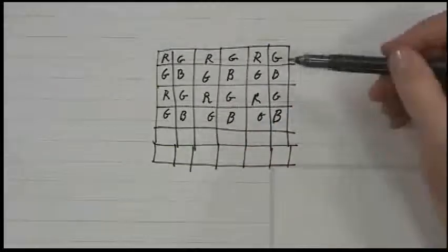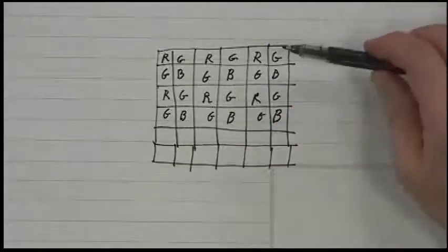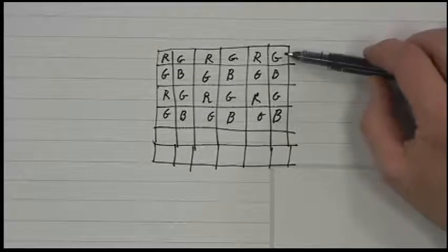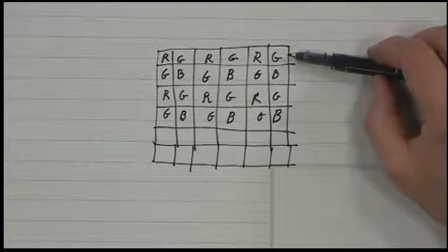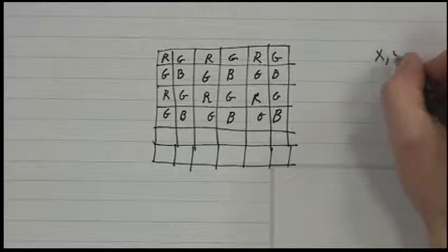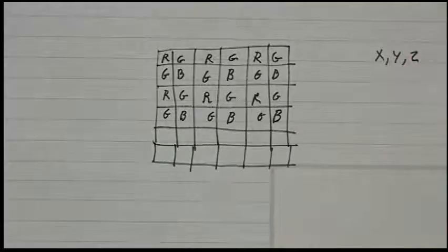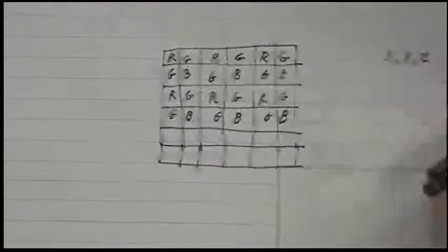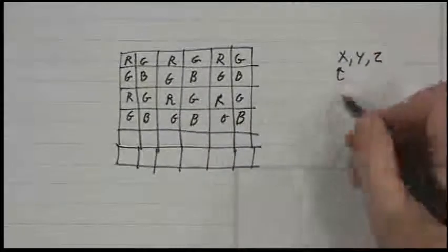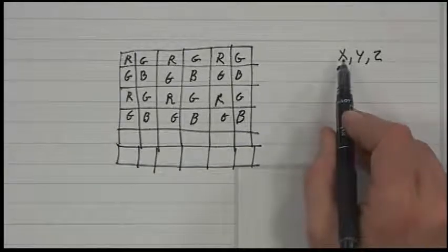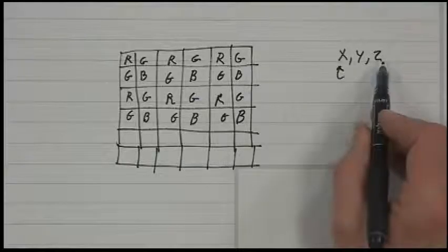Okay, now what happens is this: can you actually design the sensor so that it has a response as X, Y, and Z? Yes. I'm not sure you'd want to, but that's a separate engineering matter. But yes, you could, because you could theoretically design a physical filter that would have the response of the color matching function of X, because X is strictly positive. They're all strictly positive.